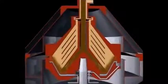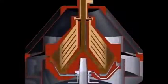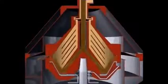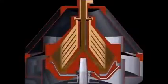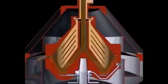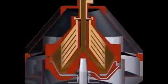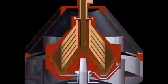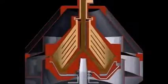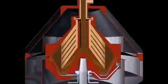Oil containing solid impurities is fed in and thrown by the centrifugal force to the side of the rotating bowl. Then, clean oil which contains little or no water is achieved in a clarifier bowl where the impurities and water collect at the bowl periphery. Heavy solids present in the oil pass through the oil to the bowl side and accumulate near the bottom. Thus, the less dense particle, which is oil, rises towards the top and to the outlet connection. In brief, the removal of contaminating impurities from the lubricating oil will reduce engine wear and possible breakdown.